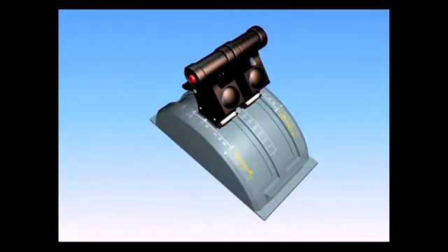We have just seen one way to turn the autothrottle off, by setting the thrust levers back to idle. The other method is to press either one of the two autothrottle instinctive disconnect push buttons located on the thrust levers. Note, pressing at least one push button for more than 15 seconds will inhibit the autothrottle for the remainder of the flight.